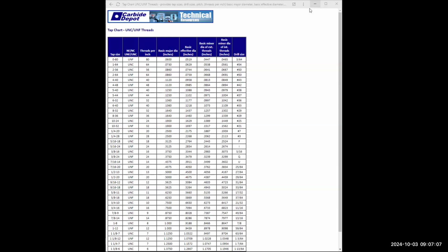So it says this hole goes 3/4 of an inch deep. So I'm going to draw a line right here at this intersection, straight across, arbitrary distance, click, enter. Then I'm going to offset, enter, 0.75, enter.